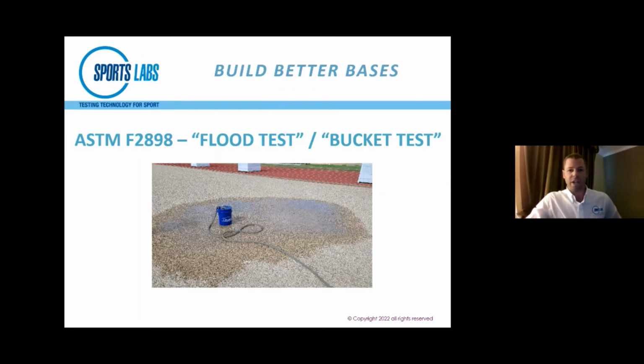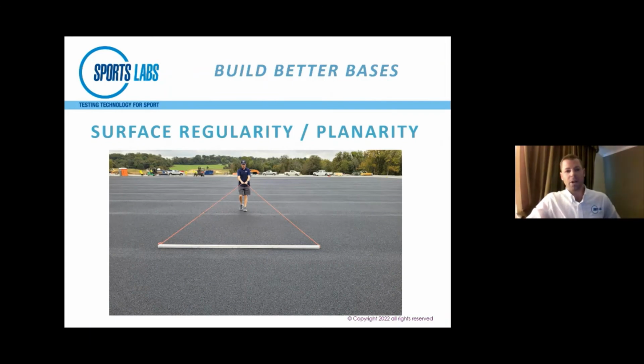Moving on to planarity, the way we check this, we've got a 3-meter bar that we drag across the field, and we cover every square inch of it. I know that there's other methods that are used, such as string line methods. Those work well,